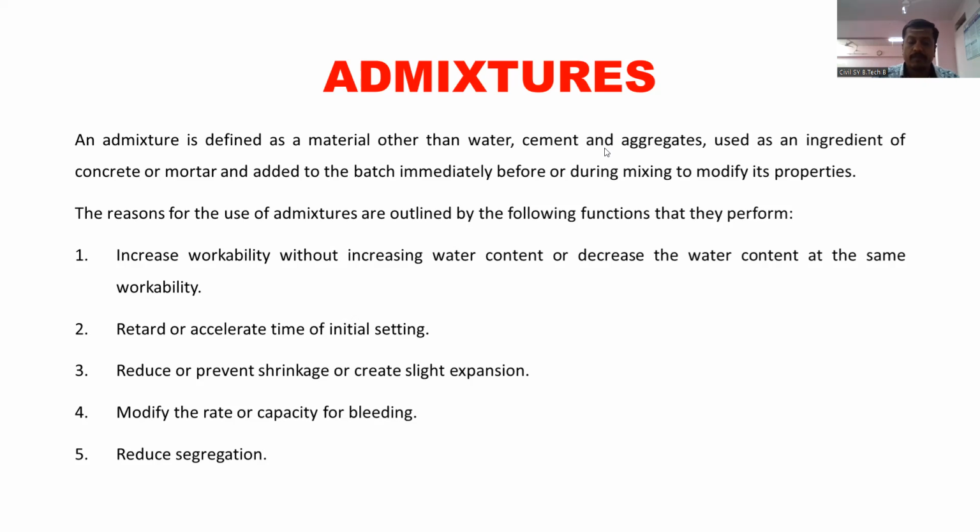Their basic functions I think we discussed in yesterday's session: to increase the workability without increasing the water content, that is by keeping the water content the same, or maybe we increase or decrease the water content. In most of the admixtures we are using now, we are going to decrease the water cement ratio.